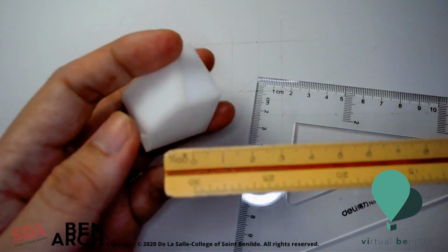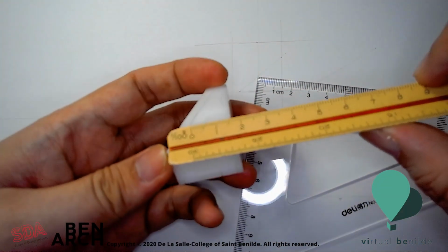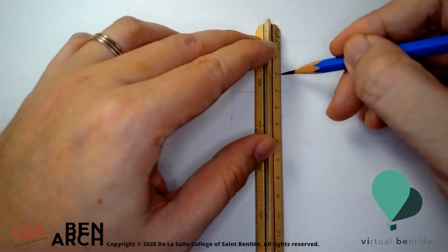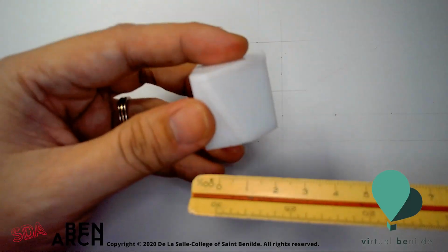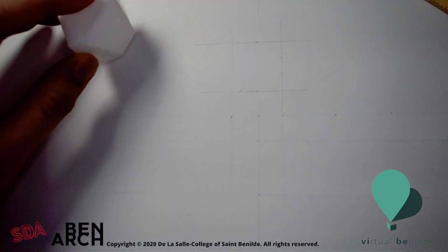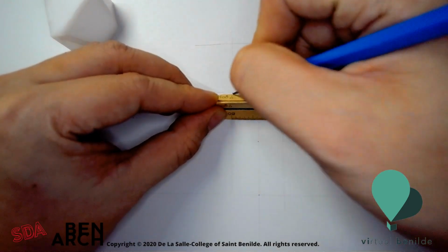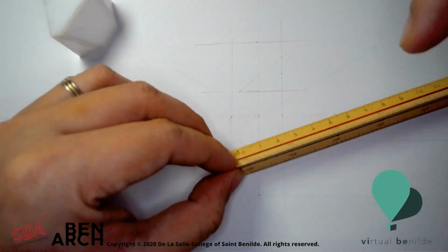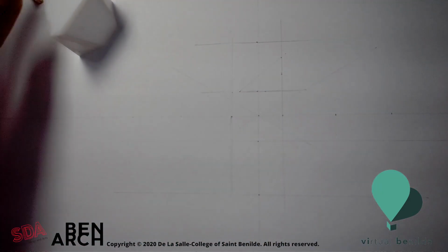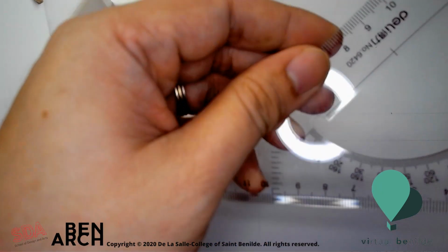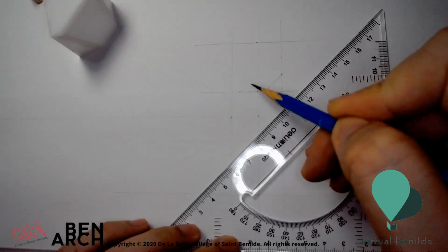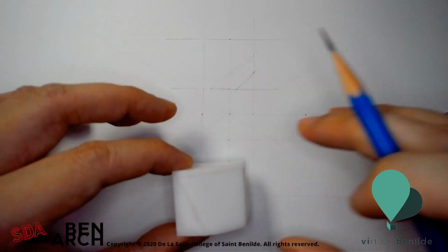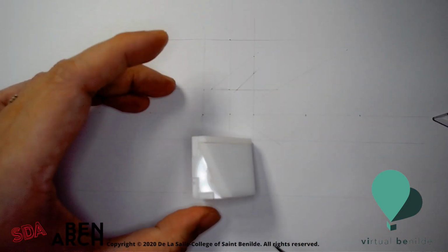But first, of course, measure. So I mean that here, this distance is 2 meters. So I measured 2 meters here, place where the dot is supposed to be. And this is another 2 meters. 2 meters from the corner is here and here. Of course, that's 45 degrees. The 45-degree triangle. So this is at an odd angle. This is not 45 degrees. And of course, now you could create the front elevation of this.